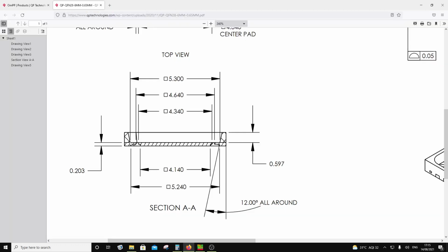Okay, so this is basically 0.53. So 6 minus 0.5, 5.3, 6 minus 5.3, and I have to start from that and then extrude out with an angle of 12 degrees. So that's what we are supposed to do. This is at 12 degrees, right? So we have to extrude out with an angle of 12 degrees. So let's do that.